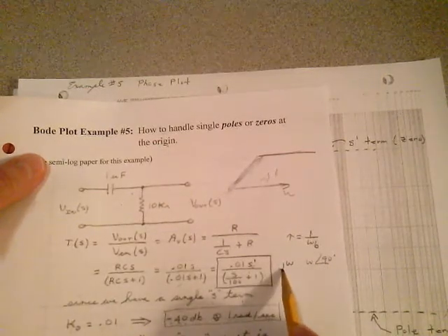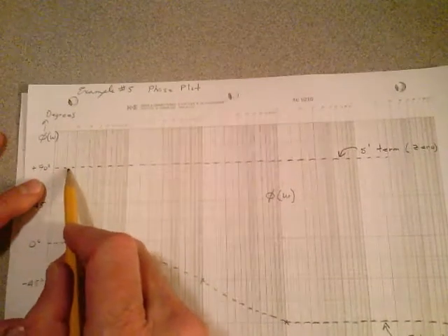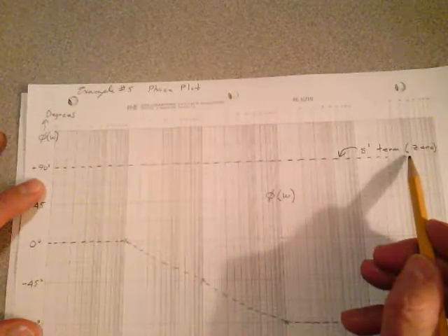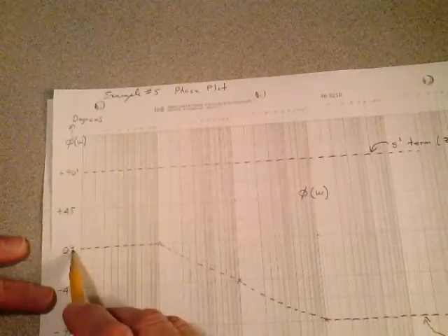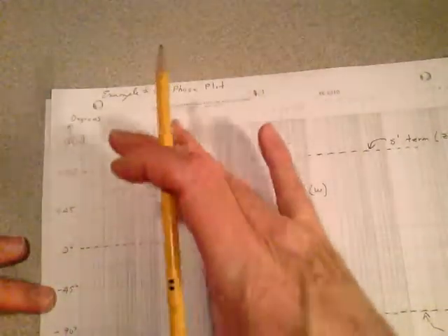That's a constant, j. So I put a dashed line in at +90 because there's a single S term right here. If that was S squared, that would be a +180. If that's an S to the third, that would be a +270. You have to relabel these axes accordingly. You have to get smaller here in your increments per division to accommodate all that. But right now, we'll probably just go to single S terms, maybe double S terms, but that's the contribution of the single S term. It's a 0 in the numerator, so it's always +90.